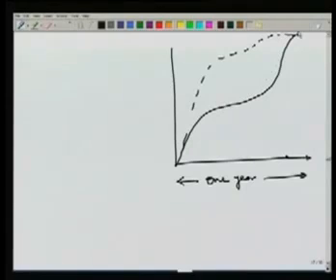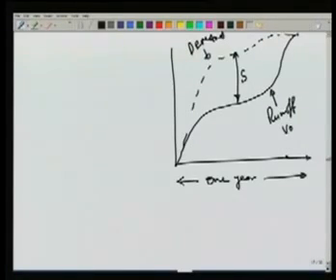Water supply, of course, changes. So in that case, what we do is we find out the maximum difference between the demand and the available water, which is the runoff, cumulative runoff volume. So the maximum difference between these two ordinates will give us the required storage capacity.